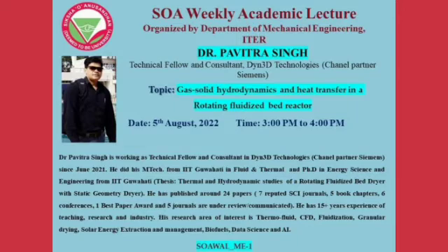And these are the boundary conditions. Actually I have used 8 air inlets, so for each and every air inlet I applied the velocity and the temperature separately, and then I selected the solid in the geometry, meaning the reactor, and then patched it with a volume fraction of 0.58. Then I ran the calculations, and I got this result. So you can see this graph.